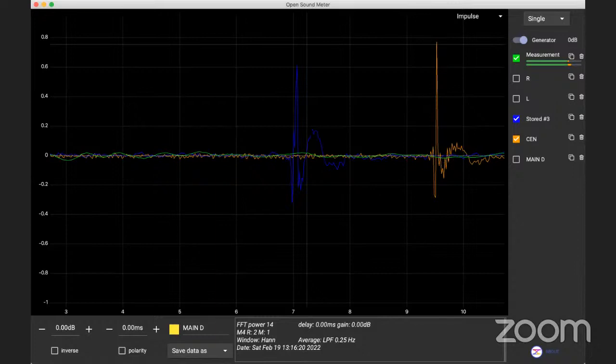Okay? So it's not only for live sound, it can be done when you're setting up acoustics no matter where you are. You can use a simple software like Room EQ Wizard or Open Sound Meter and do a very simple setup and understand what's going to happen once you place speakers somewhere in the room. Okay? So making sure that whenever you're sitting in the sweet spot, you're sitting at a point where both the left and the right speaker meet exactly in phase.